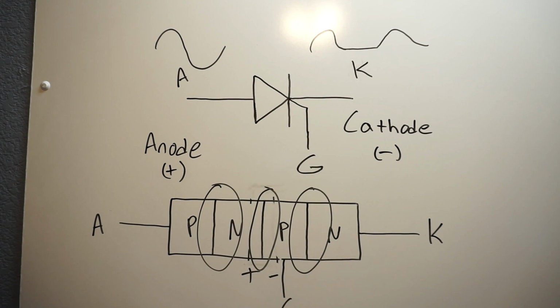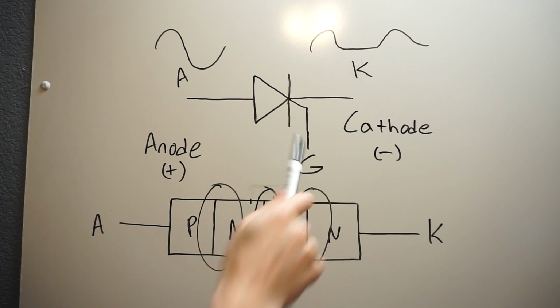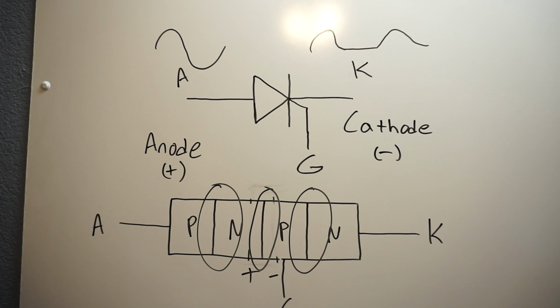One thing you guys might see is we can actually use this as a switch in an AC circuit. It can behave as a solid state switch in an AC circuit, kind of like a relay, and that's oftentimes what they're used for, because relays are mechanical components. They can fail, and they also have things like arc over, your contacts can weld, things like that. There's issues like that, so oftentimes you'll want to use a solid state component.